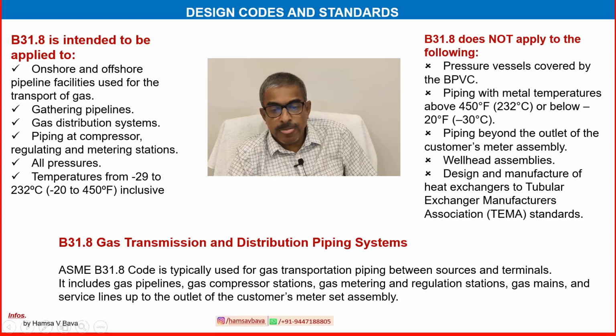It does not apply to the following: pressure vessels covered by the BPVC, piping with metal temperature above 400 degrees Fahrenheit or below -30 degrees C (-20 degrees Fahrenheit), piping beyond the outlet of the customer's meter assembly, wellhead assemblies, and the design and manufacture of heat exchangers, which follow the Tubular Exchanger Manufacturers Association TEMA standard.